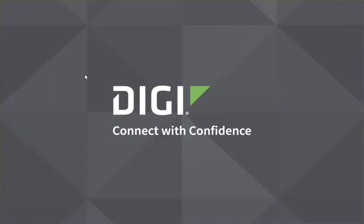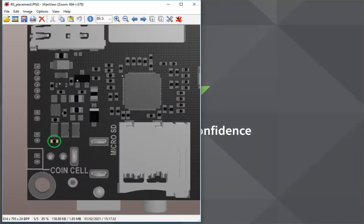So let me show you how to do that on the real board. The first thing is to locate where R8 is on the board, and you need to look at the bottom side of the CC6UL SBC Pro, and near the microSD card holder you will find R8. So you need to remove it, or depopulate it.